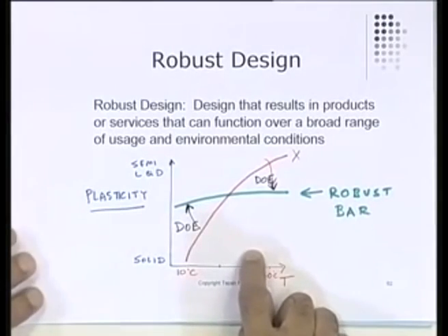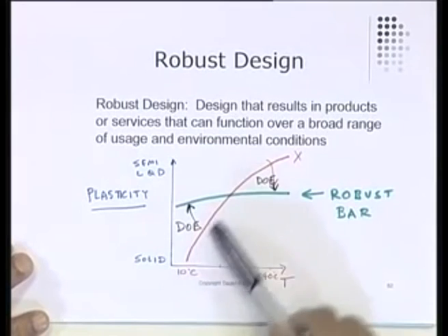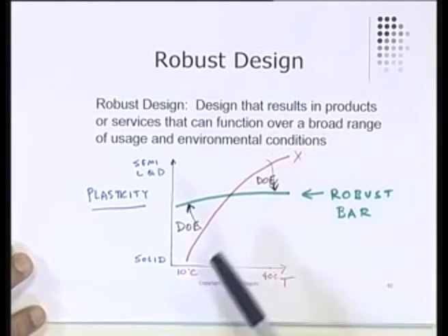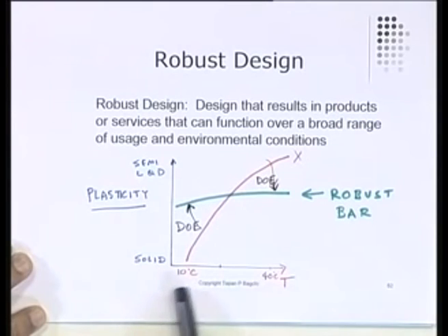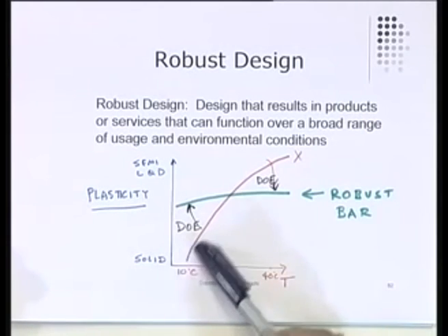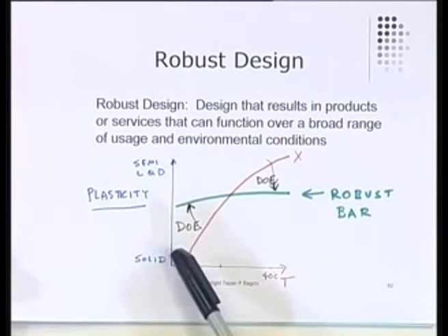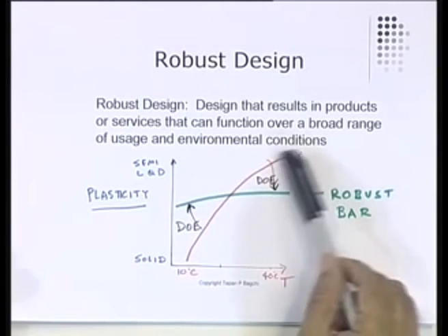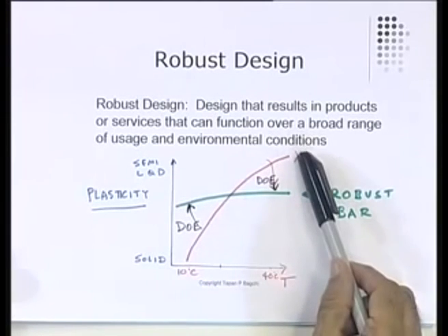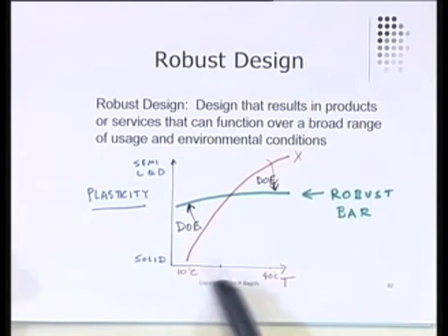In the case of our robust design, remember this picture that I had there? Here, the design variables would be all the things that go into the chocolate bar. And this is my ambient factor. So what Taguchi said is, when you're trying to produce a robust design, do not only manipulate these design factors, but also manipulate this and look at the total response. Look at the total response, which is now the composite, and it is indeed the interaction of the effect of the design variables, and that of the ambient condition or the noise condition.